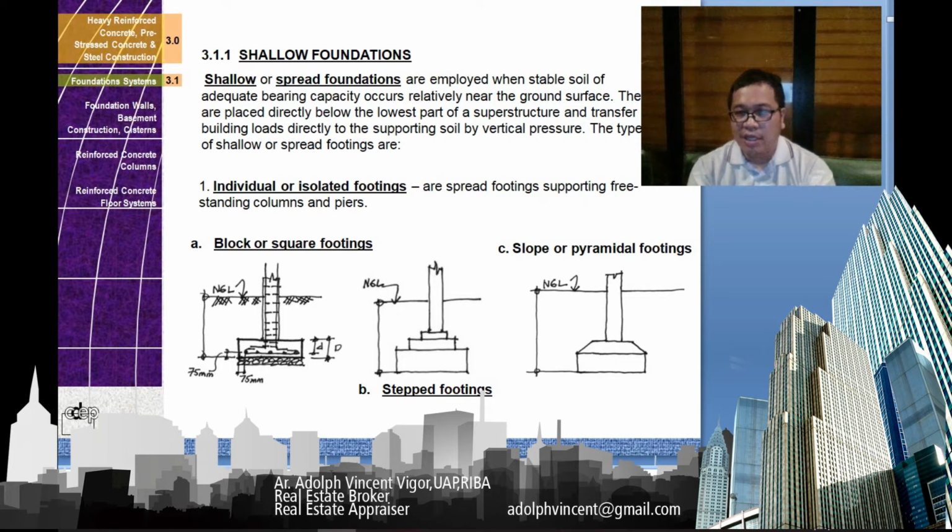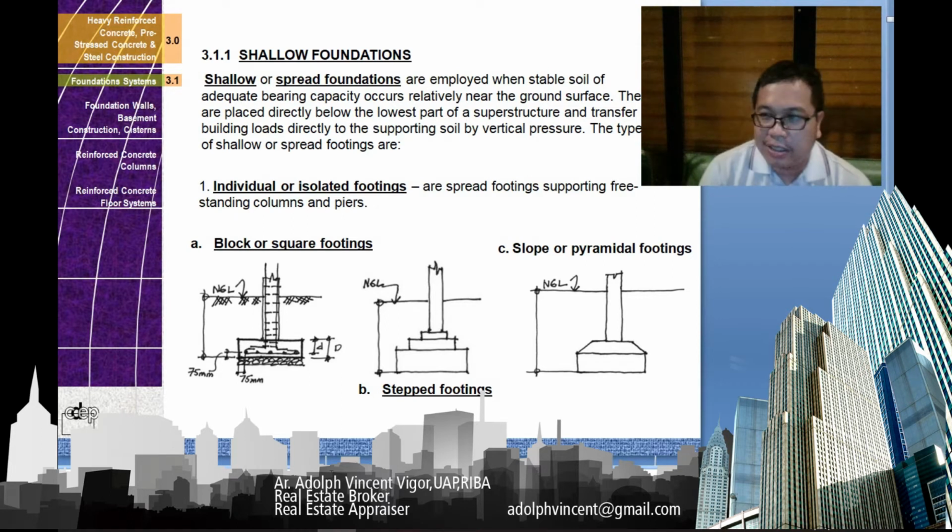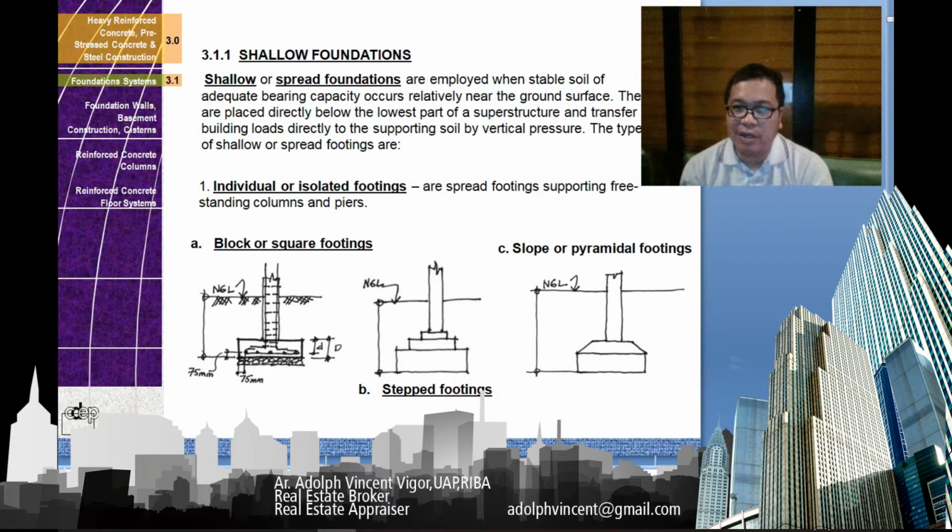That is why you should try to do structural analysis first, or try to get a history of the area. Structural analysis is really important, and geotechnical analysis also. So you get a sample of the soil and determine if there is a stable soil stratum underneath.